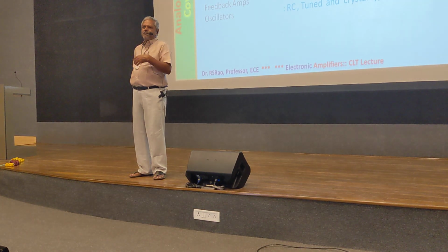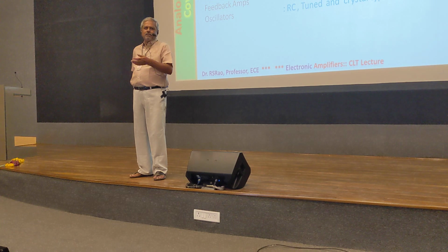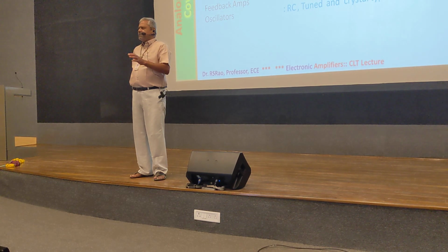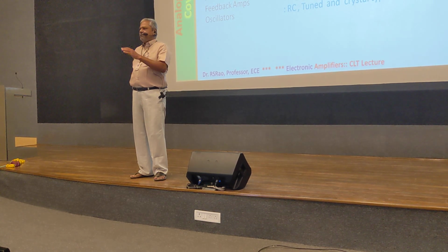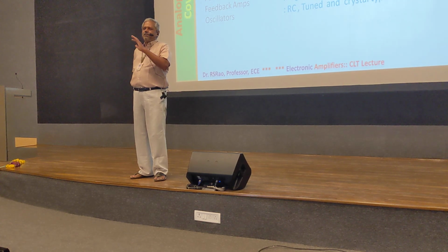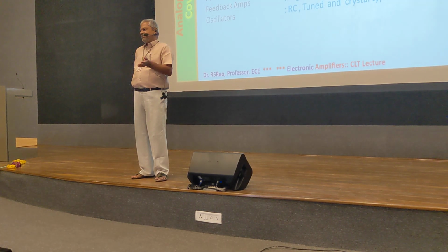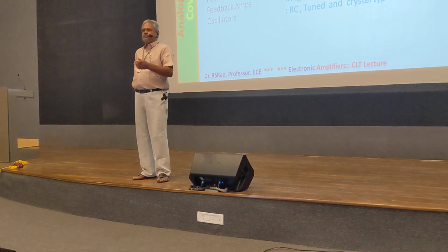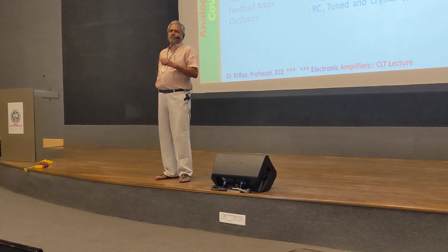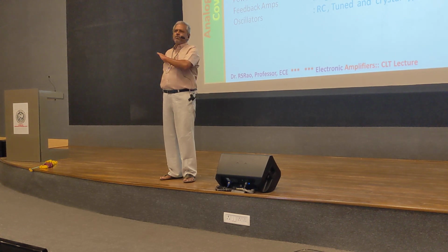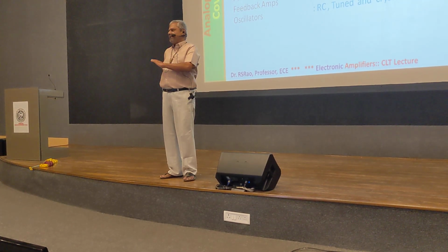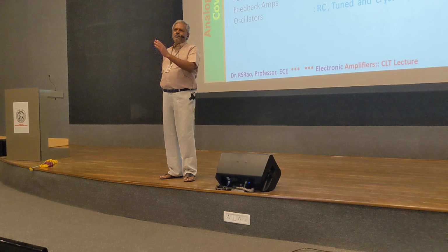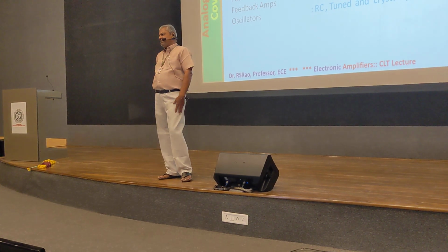Or if you consider Thevenin's theorem, Norton's theorem, Tellegen's theorem, any theorem, all those theorems and laws which you studied in circuit theory are valid for linear circuits. But as it is, amplifiers are nonlinear because a transistor or diode is inside the circuit. So those laws are not useful for the analysis of amplifier circuits.